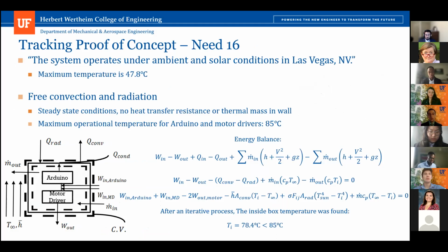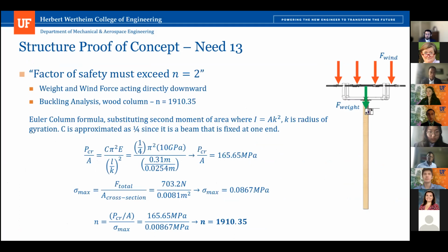But I do like that you're considering it and you're sort of on the right track there. I'll jump back to the structural analysis. You were doing structural analysis and calculating factors of safety, and it wasn't clear to me because, again, Las Vegas is hot. It's certainly much above room temperature where material properties tend to be calculated and reported. But you also find temperature knockdowns: as temperature goes up, the yield strength of a material will go down, right? Did you consider any of that in your structural analysis here?